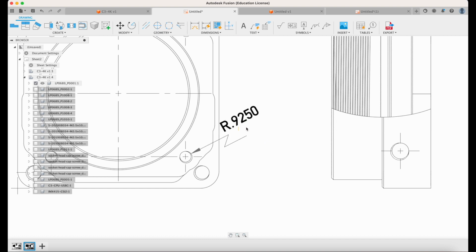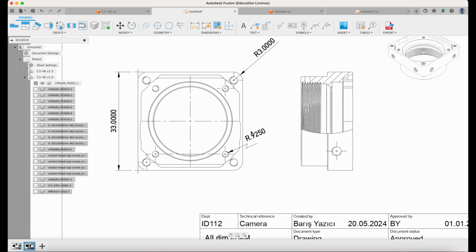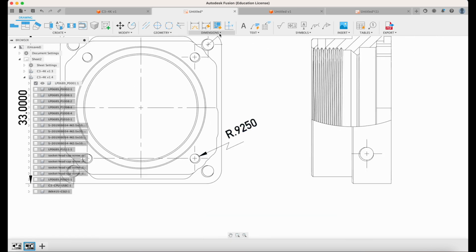I don't want to touch the original drawing, so I want to make sure that the jagged line and the dimension are not touching. So that's another way to put a circular dimension. Actually, let's try the fillet again and see if it's fixed. Fusion sometimes gets stuck. Let's click this, and then we'll try and correct it.